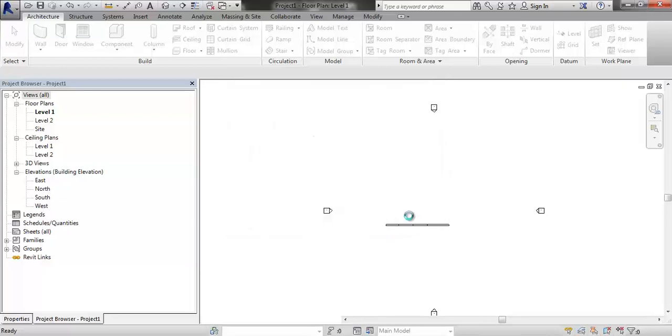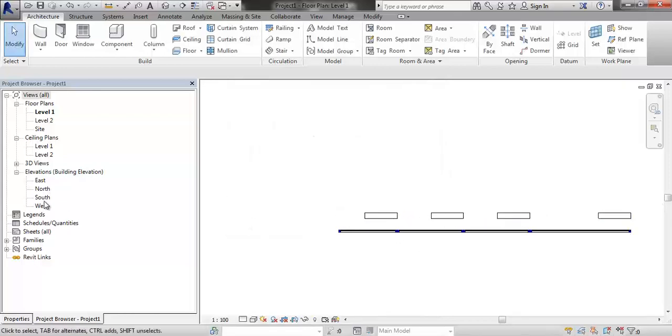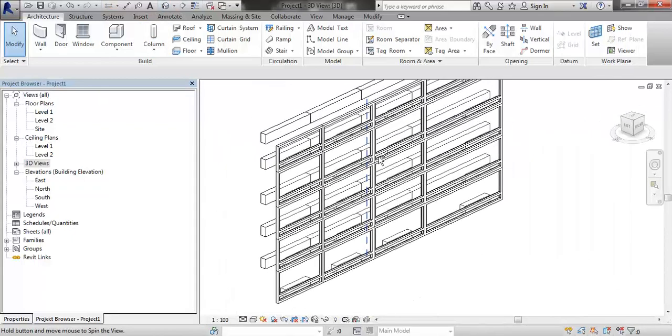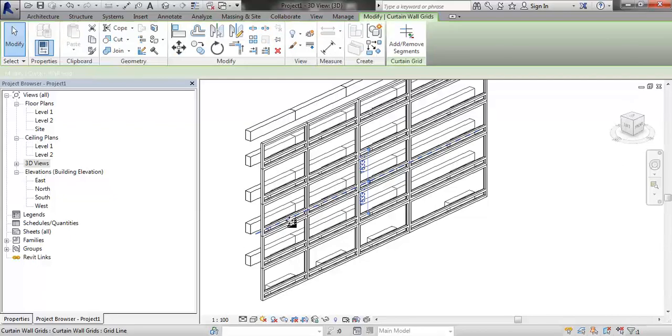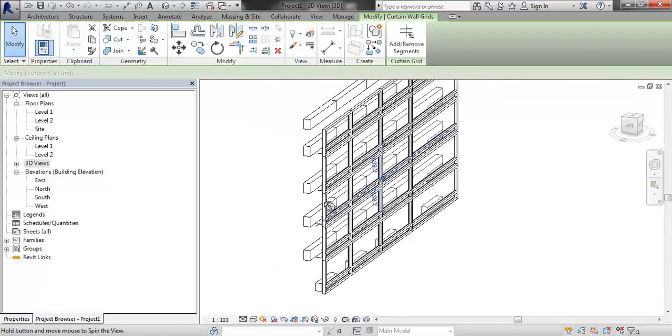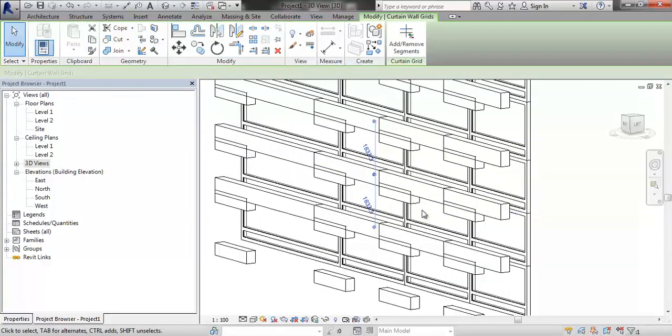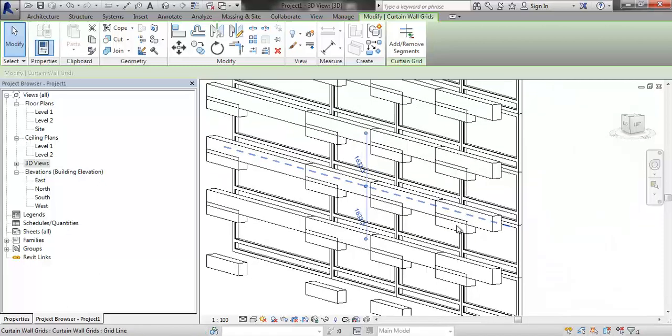I'll overwrite that existing version, and then when I go to my 3D view, you'll see that I have my panels. Now, in this case, I have slab edge running over, and I have some overlapping, right? So that's a problem. So how we handle that condition is I need to make a panel top, a panel bottom, a panel left, and a panel right, because in certain ones, I'm going to turn off the slab edge. So panel top would only have the slab edge at the top.